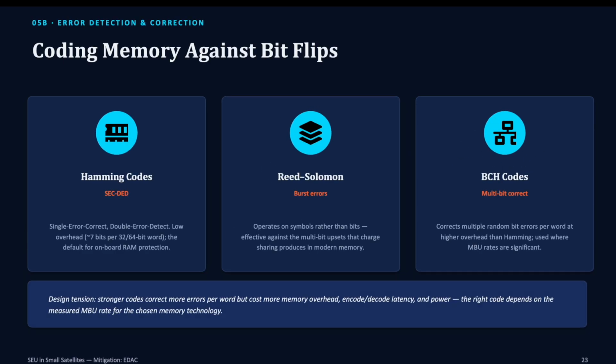So in coding memory against bit flips, we have Hamming codes, Reed-Solomon, and then BCH codes. So the Hamming code is a single error correct, double error detect. And the Reed-Solomon operates on symbols rather than bits. And the BCH, it basically corrects multiple random bit errors per word.